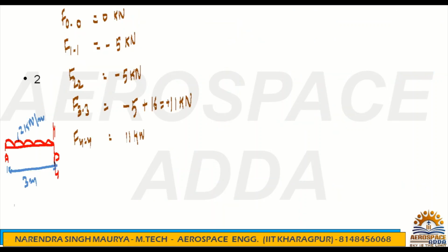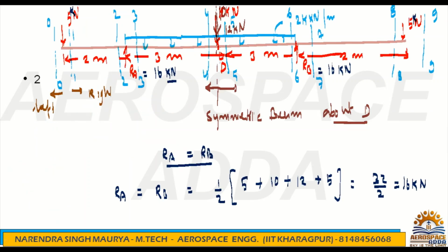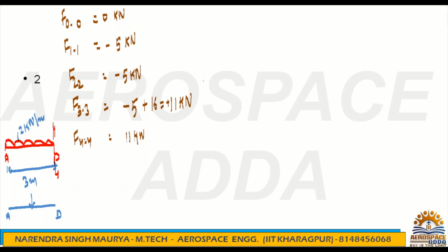If you convert this to a point load, what will the point load be? This is A, this is D, and the point load will be downward, because you can check the forces are going downward for the UDL. So it will be downward 3 into 2, which becomes 6 kilonewton.